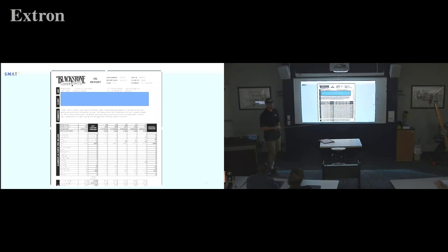They'll actually give you a little commentary about what they saw in there, because we probably don't know how to read them. So who can tell me, I know it's a little bit hard to read, but when did he switch oils? He switched from a multi-viscosity to a straight weight. Anybody?